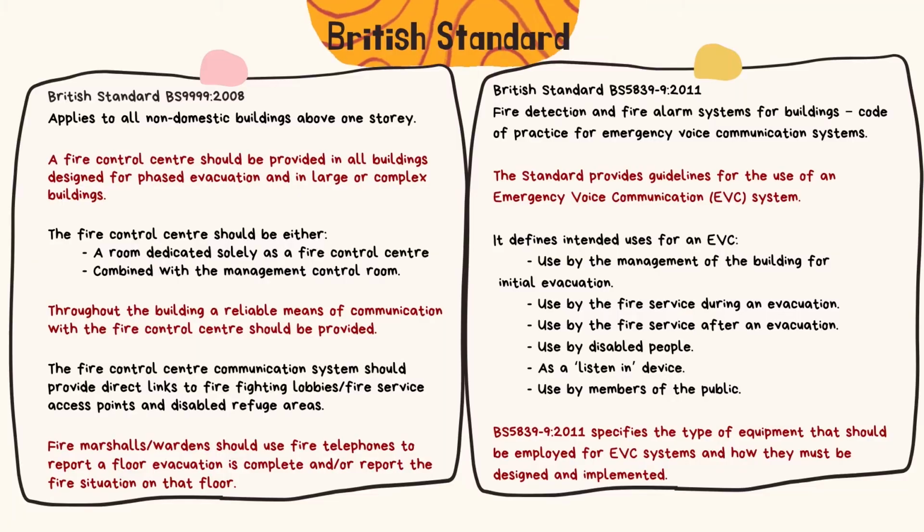Second, used by the fire service after an evacuation. Third, used by disabled people. Fourth, as a listen-in device. And lastly, used by members of the public. For EVC, it can be used by all people that use the building. BS 5839-2011 also specifies the types of equipment that should be employed for an EVC system and how they must be designed and implemented.